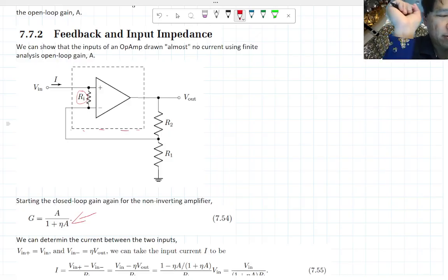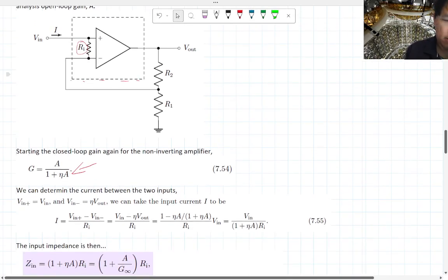There's a bunch of transistors and capacitors and some resistors connecting them together. It's more complicated than just Ri. But we're going to model the input impedance of this op amp directly, based on how much current goes from the non-inverting input to the inverting input. You're going to see how this changes.